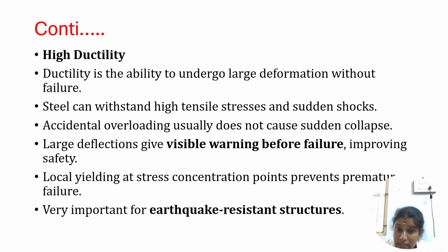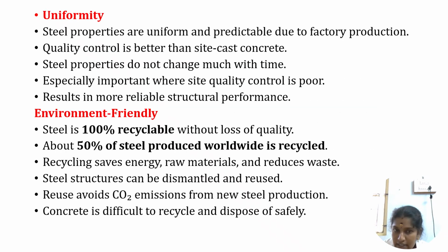If you use ductile material, it can withstand any sudden load, seismic load, wind load, earthquake load. Everything can be withstood, and the structure will not collapse. So this is the high ductility compared to concrete. Next is uniformity, and it is also environmentally friendly. Steel is 100% recyclable without loss of quality; it does not change the quality.